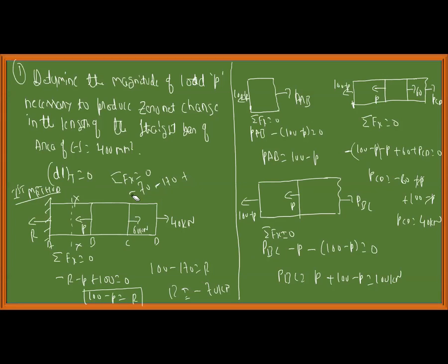If you club the summation of these forces, R is equal to minus of minus 70 minus 170 plus 60 plus 40. Therefore R, what we have got, minus 70 is acting in this direction. Then you will get 60 plus 40 plus 170 minus 170, which should be equal to 0. The summation of forces should be equal to 0. Have you understood this? Yes, sir.